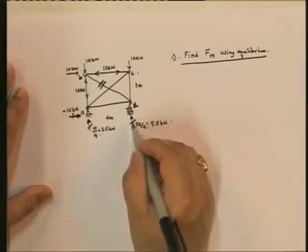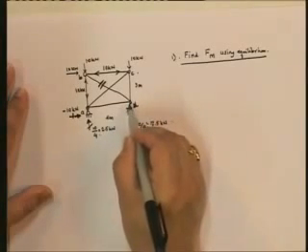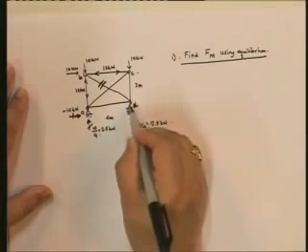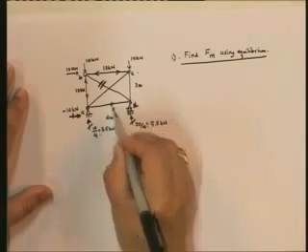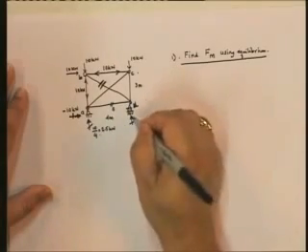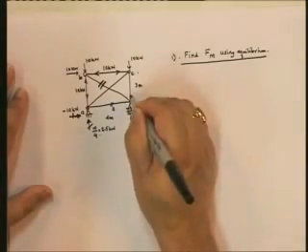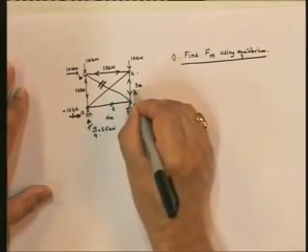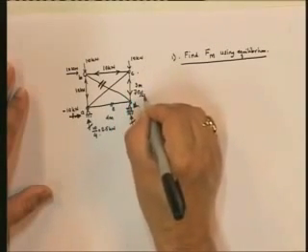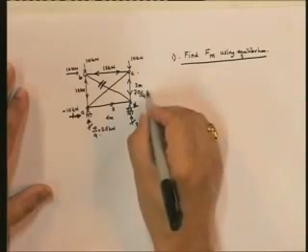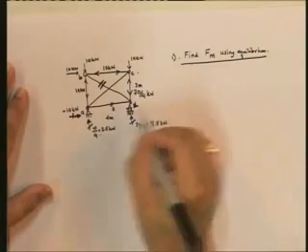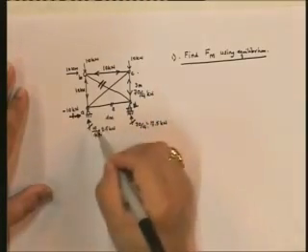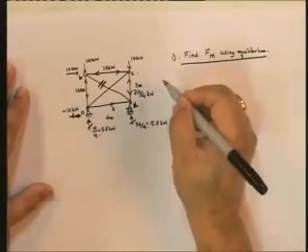Here if you look at it, sigma Fx equal to 0 gives me what? This has no force. And if I find sigma Fy equal to 0, you will see that this is equal to 70 by 4 kilonewtons. So compressive force, this is 0.